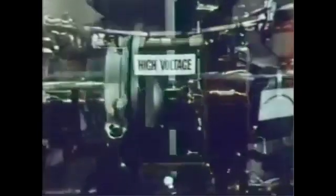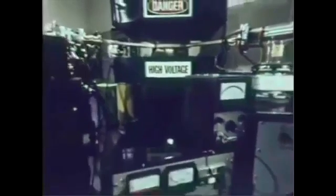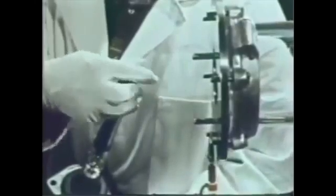As an example of our research in IC technology, we're studying new ways for getting impurities into semiconductors. Normally, this is done by diffusion. We do the same thing by ion implantation. This machine takes individual ions and accelerates them, ramming them into semiconductor material much the same as you would shoot a bullet into a bale of hay. Right now, this is a much more expensive process than diffusion, but it's a different technique.